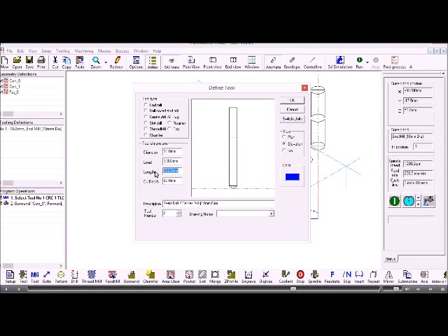The tool length, again, doesn't really matter, it's just for a visual thing for the tool on the screen. When the drilling takes place, the system will automatically add the lead value here onto the Z value that we give it, but there is a switch in the drilling dialog box which will switch that feature off, which I'll show you in a second.